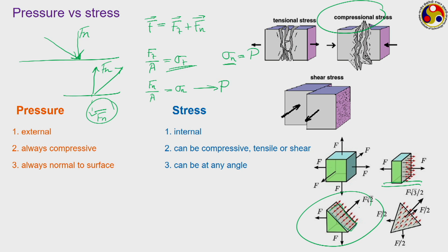So, the pressure force will always be normal to the surface, and the magnitude is direction independent, or to be more specific, pressure is a scalar quantity. Of course, the force associated with pressure is a vector like any force, but pressure itself is a scalar quantity, because at a particular point the magnitude of pressure remains the same coming from all possible directions, and that is why pressure is a scalar quantity which does not have any direction dependency.